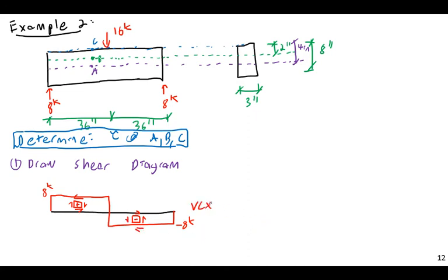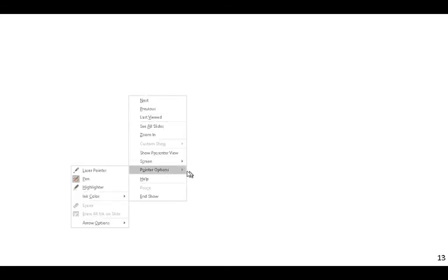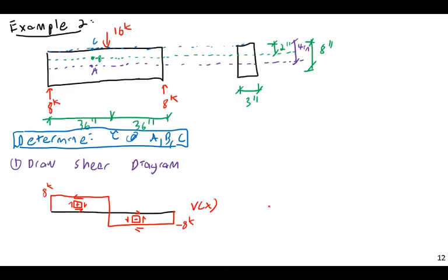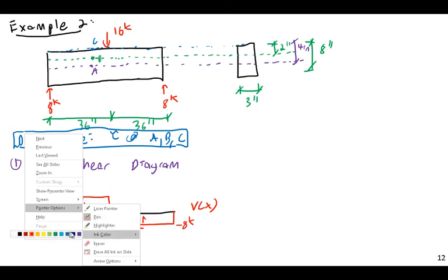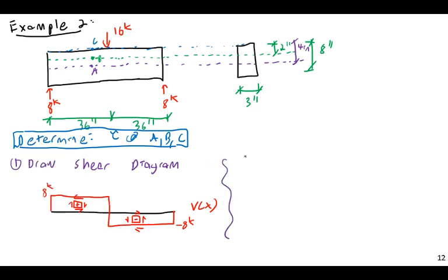V as a function of x. So next, basically we're going to have to design for a V of 8 kips. Now I need to find some Q's. Well, actually, first, even back on this last slide, I think I can squeeze in to find I. That's not that bad. It's just a rectangle. To find I.